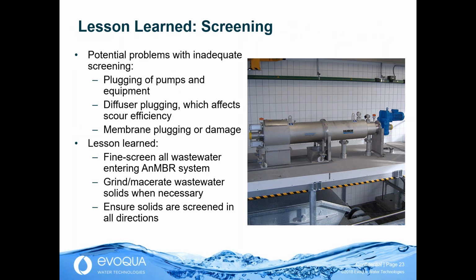Another lesson we've learned with the systems that I discussed there is the importance of screening. Screening is important because all anaerobic MBRs have potential to flood in different locations, whether it's in between the membranes for flat sheet or in the fiber bundle for the whole fiber membranes. There's also potential to plug diffusers and pumps if the wastewater is poorly screened.